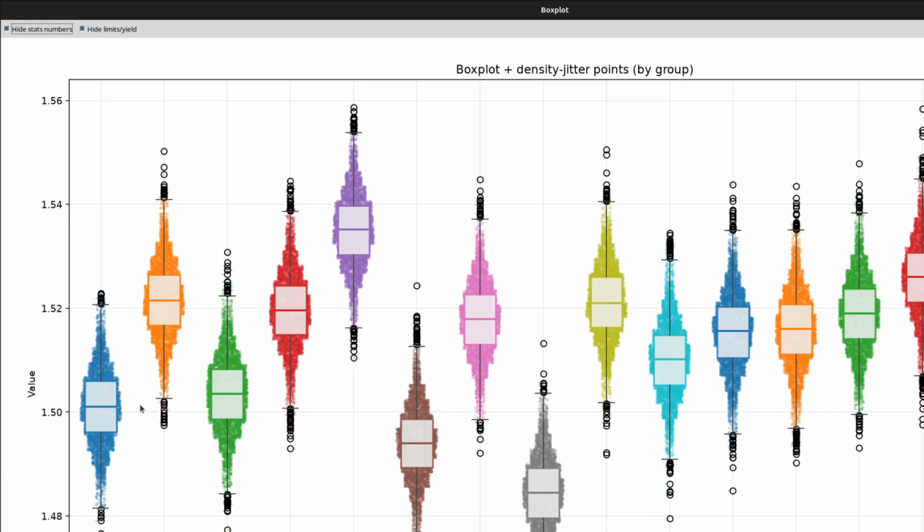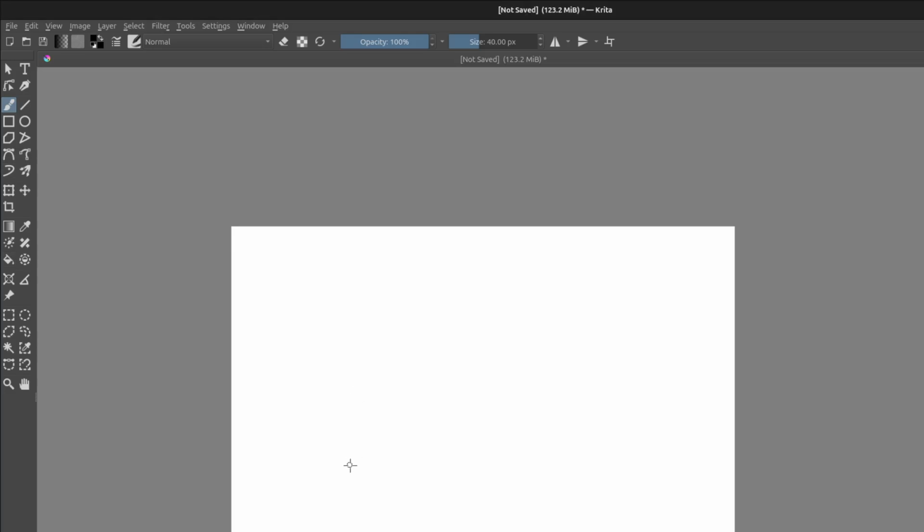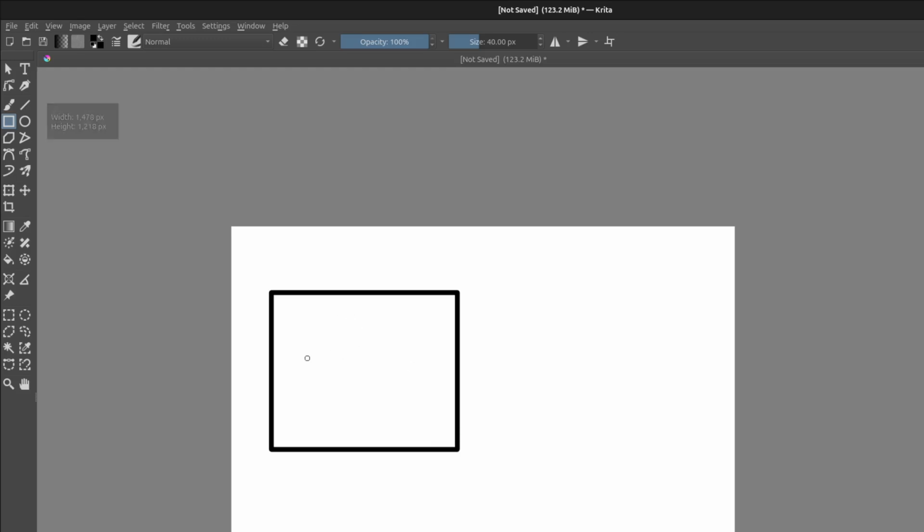But because this is staggered like this, that means there's kind of two things here. When you've got a mold, you've got two sets of parts that are made. You've got a mold, and then you've got a bunch of cavities in that mold. These cavities here can be misaligned in X and Y for each single one of them.